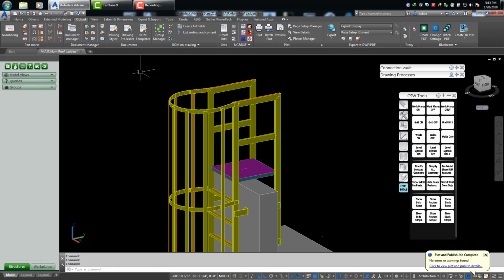of the box. So you'd be best served to create your own, and in order to do that, you have to acquire a deep understanding of the drawing style manager, and especially how model roles of the objects are used. And you can create your own model roles to make dimensioning requests more precise. But we'll go over some of that here, and I'll show you exactly what I'm talking about.